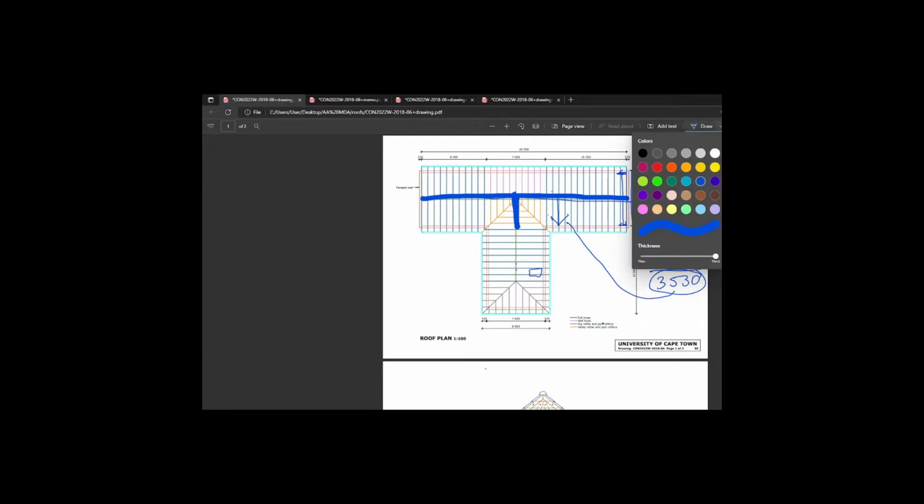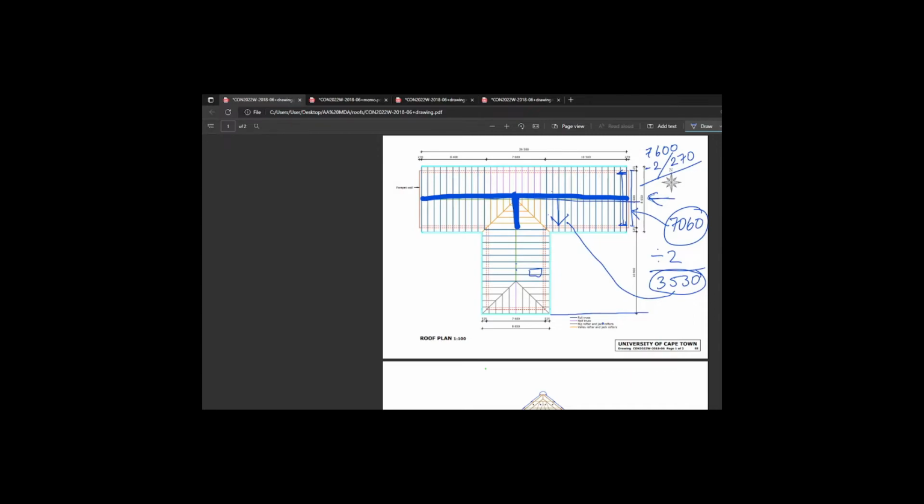So since we've come to the inside face, what else can we steal from the drawing to give us more information on what's going on here? Well, this again is not so obvious. 10,900 will take you to the edge of the roofing, but it doesn't take you to the inside face of this brick. So you have to make some assumptions again. 525 is our eaves distance on flat. We are going to assume there's also 525 that way, right? Here's 525 as well. 525 that way.